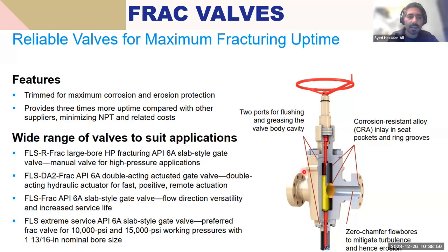So the reliability of the frac valves, these are the valves in the frac stack, is very important, because these are the valves providing you the barrier, preventing the wellbore fluid from being exposed to the surface or having an uncontrolled exposure. So a lot of emphasis is put on the design and development of these valves, so that we have more uptime on the locations, we reduce the maintenance cycles, we have erosion and corrosion protection, while reducing non-productive time, or NPT, and the related cost.